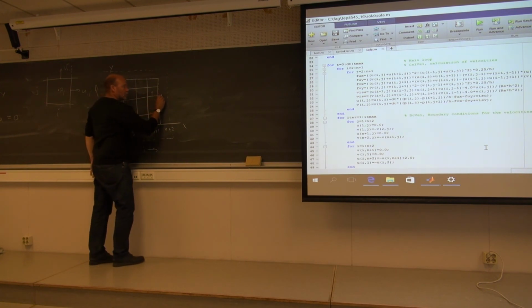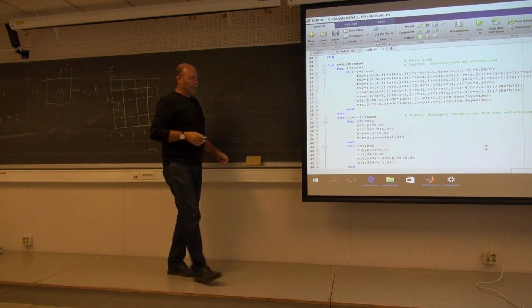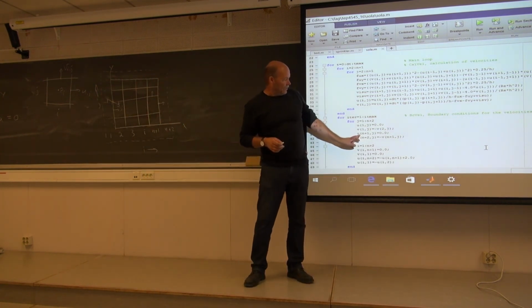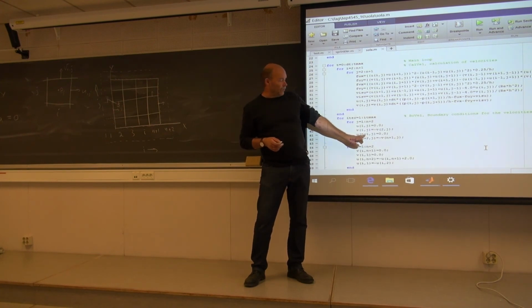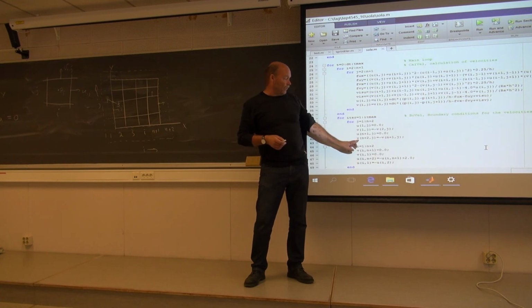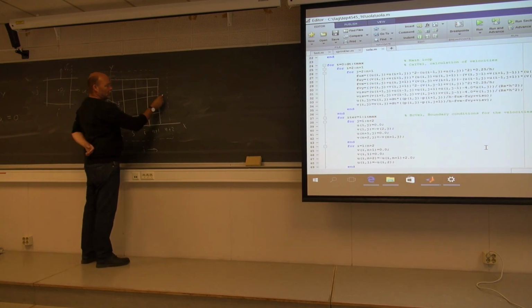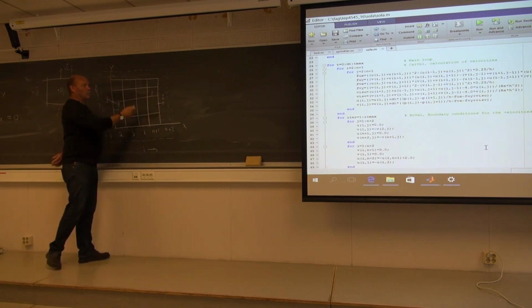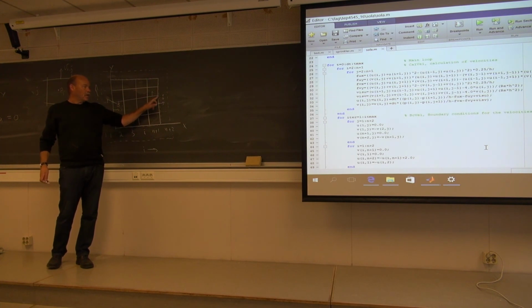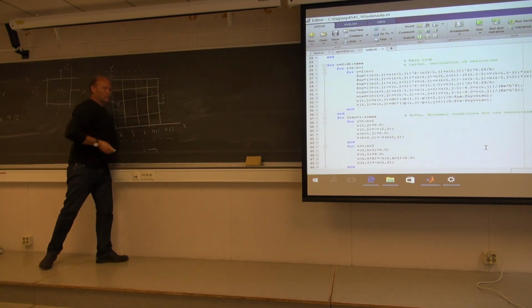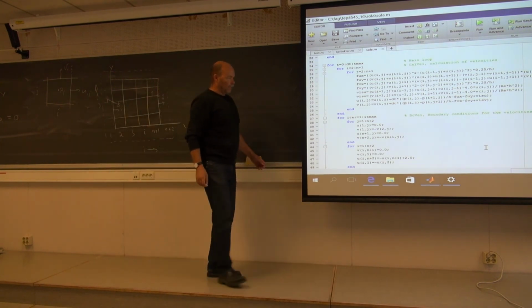For the boundary condition, I'm going to need Vn plus 2. So you see it's a little messy with this staggering mesh. Here it's a boundary condition for un plus 1, but here is boundary condition for Vn plus 2. So yes, it's messy, but unavoidable. So yes, we have to specify the velocity in the y direction here, half a cell inside the wall. And we do the same as we did on the other side. Make him negative to the 1, whatever might be inside the domain. So you have 0 in between them. Because we want to have 0 velocity alongside the wall.